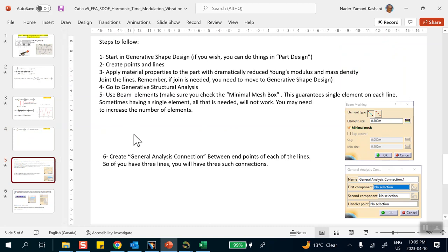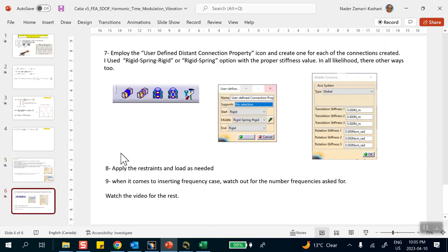Now, these next two slides are put here because they show the steps that I follow in order to go from the initial point all the way to where you want to plot the displacement. And here's the second one. Now notice that unfortunately, if we want to do a simple mass spring system in Catia, you have no choice but to actually create some kind of a regular element. I've chosen to do beam elements, and without having an element, you won't be able to define the stuff that's needed to basically describe the spring and its stiffness, etc. So you'll see what I mean.